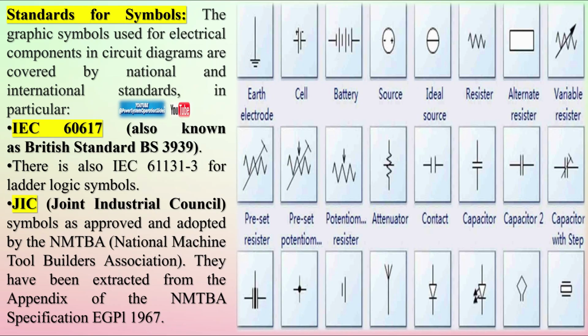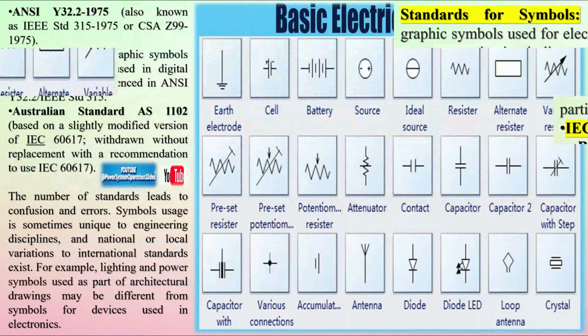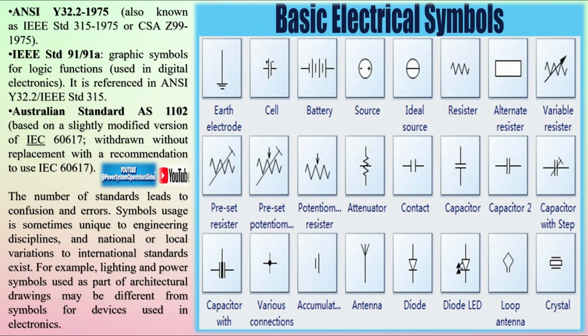Diodes, including bridge rectifiers, are shown using triangles pointing to a line, indicating the direction of current flow. Inductors are drawn as coiled loops, and transformers as two sets of such loops separated by lines. Sources of power, such as batteries, are depicted as alternating long and short lines. Ground symbols indicate the reference point for a circuit, and switches are illustrated with breakable lines to show their open or closed states.